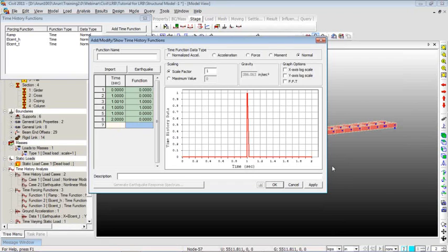We created similarly. You can create any user-defined function and apply it as an impact load. But since we say impact load, it is like it touches and it vanishes. So therefore I use such a small peak interval. But blast loading is something where the energy dissipates throughout the structure. There are vibrations originating from one point and then dissipating over the structure. So that is a little different from the impact loading.